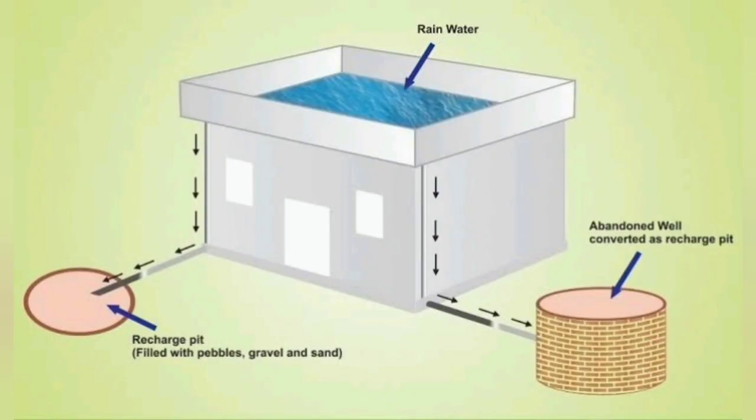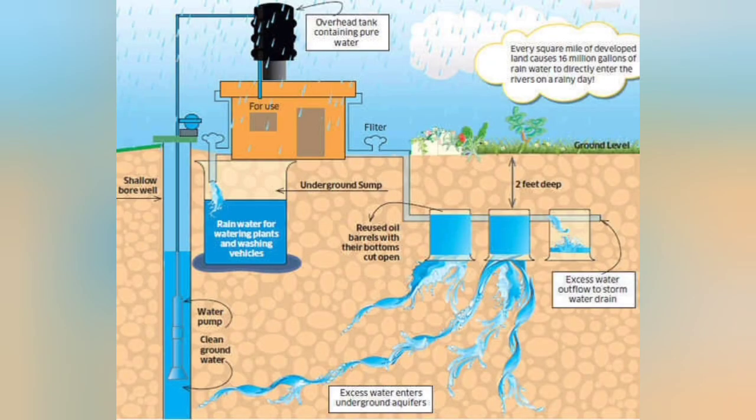the vadose zone up to 3 meters below the ground level. So the upper 3 meters of the ground unsaturated zone is not considered for recharging, since it may cause adverse environmental impact like waterlogging, soil salinity, etc. The post monsoon depth to water level represents a situation of minimum thickness of water zone available for recharge, which can be considered surplus monsoon runoff in the area.